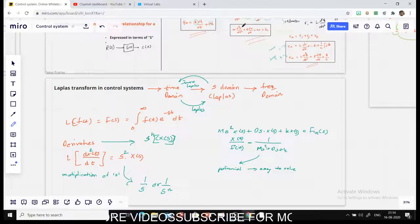That's why we basically convert everything into a Laplace transform, that is S domain. We solve it there, we try to define a control system for that, and then get back to the time domain for different outputs. So the basic reason for converting everything into a Laplace transform for a control system is converting into a simpler form, that is polynomial equations, and you can easily solve the polynomial equations for different values to understand the behavior and stability of a system.